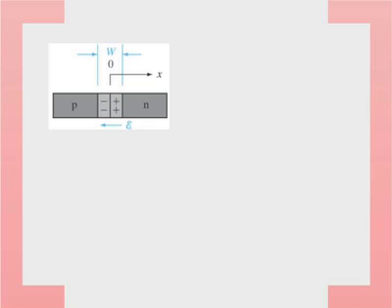So you end up generating positive charges on this side. So the holes have moved over. The electrons, of course, move from this way to this way. This is just the diffusion. High concentration, low concentration, and you generate negative charges.